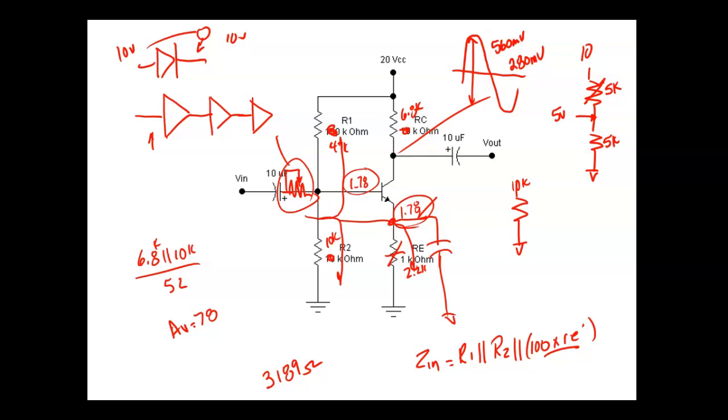And how much voltage is dropped by a resistor if it has no current flow to it? Zero. So that means I got 1.75 volts on the base, and there's no current flow through the diode to make it drop 0.7 of a volt. It's acting like a piece of silicon. It's not acting like a PN junction. And we're seeing that 1.78 volts from the other side.